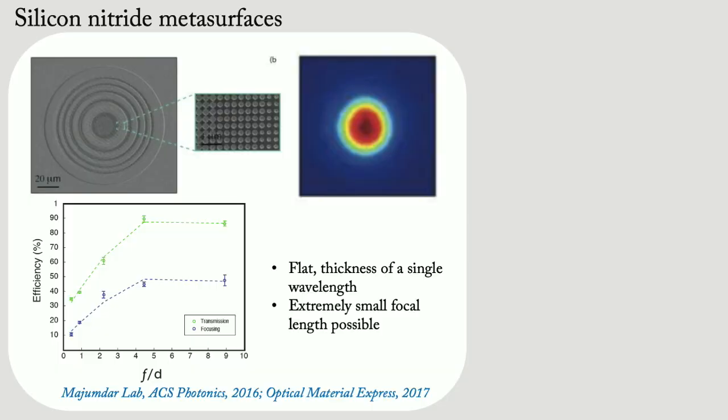So when we first fabricated this metasurface lens, you can see the nano scatterers. This is how the lens is focusing. And we'd like to point out here, silicon nitride is, till date, the smallest refractive index that people have used to create metasurface. Its refractive index is actually pretty small. It's n equal to 2, whereas mostly people work with silicon, whose refractive index is 3.5. And we have recently figured out that there is some penalty you pay when you go to low refractive index, but for almost all practical applications, it works fairly well.